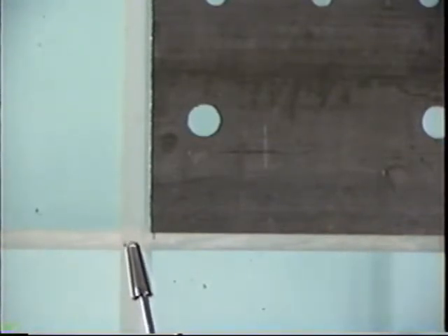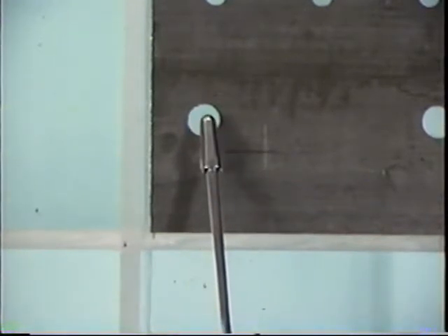So the 0 point is located off of the x and off of the y, and where that intersection is, we call that 0. So there's the 0 point. We come over from the 0 point a distance, that's our x direction. We come up this distance, that's our y direction, and by locating x and y, we use a datum reference frame to identify what a part might look like if a part were square or rectangular.